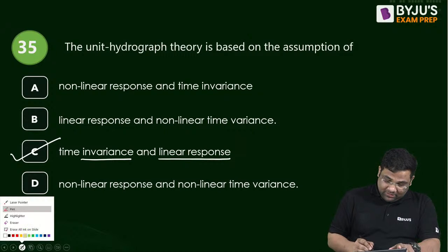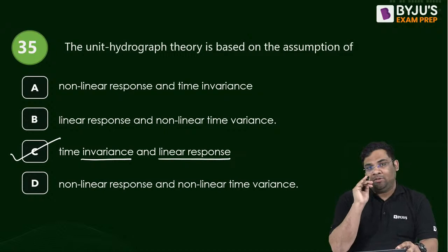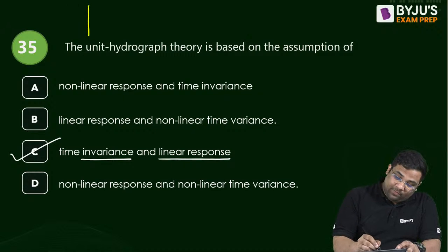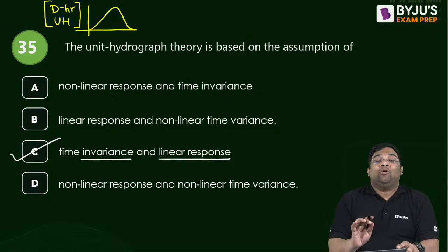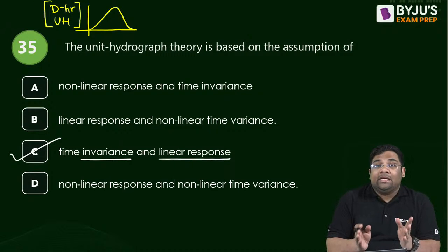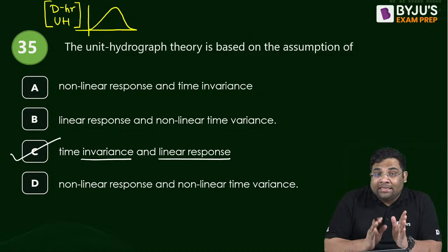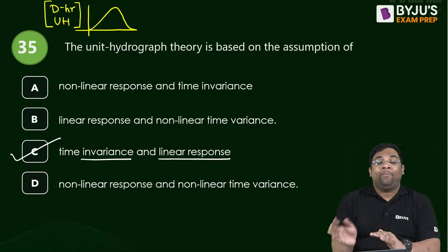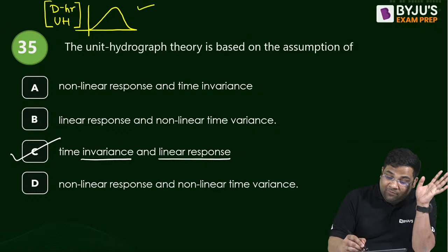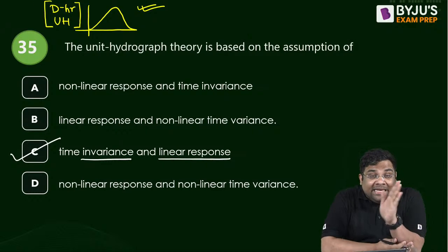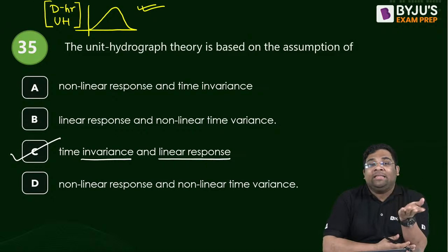What are the two terms? Time invariance means what? If you have drawn a unit hydrograph for an area, for suppose D hour rainfall, this unit hydrograph will come the same if that rainfall occurs in the month of March or April, or morning or afternoon, any time. This hydrograph will remain the same. Time invariance. It will not vary with time.